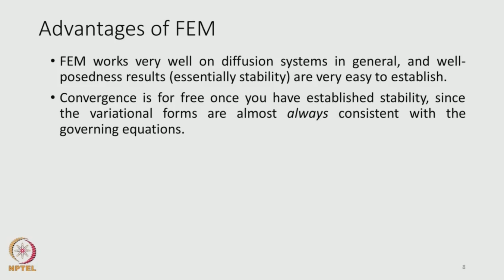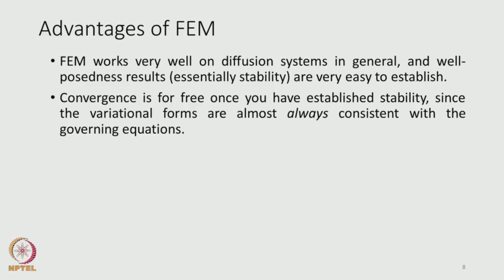There is a theorem called the Lax equivalence theorem. If a scheme is consistent and stability is ensured, then convergence is automatically ensured. That is the Lax equivalence theorem. We are going to talk about it again later. So, FEM ensures convergence because the variational form which is used as a weighting to get a weighted form, or a weak form, of the governing equation is always consistent, and we have already seen the FEM procedure mostly ensures stability.